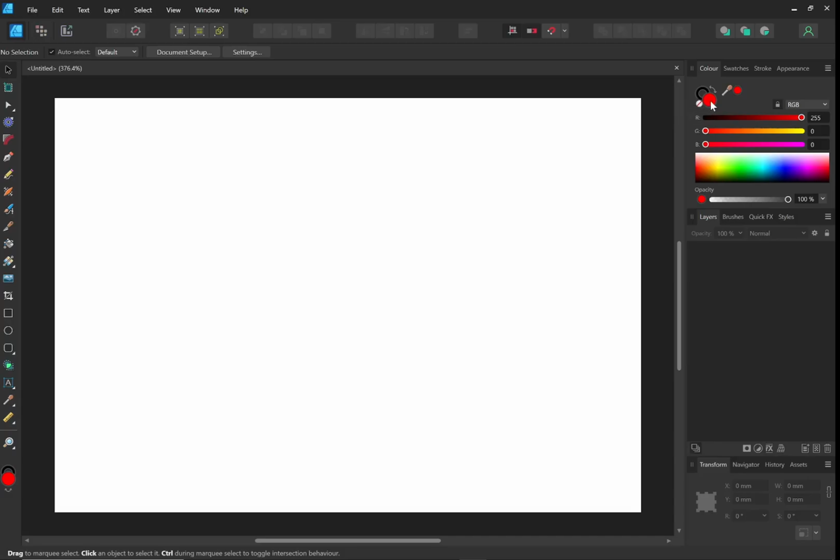So I've clicked that, and now I'm going to click the little tiny circle to the left of it that has the red line. This means do not have any fill. No fill. Click that, so there's no fill now. If we click the button at the top, they call it the stroke, which is the outside line. We're going to click that black ring, and this is when we want to drag this red all the way to the top. So now this should get us the shape that we want.